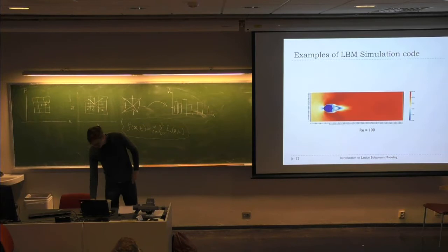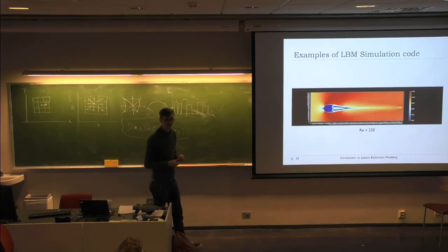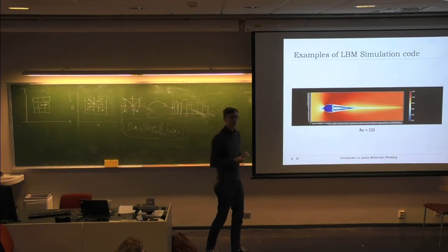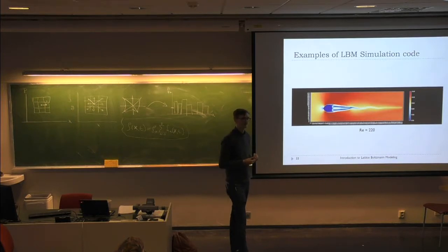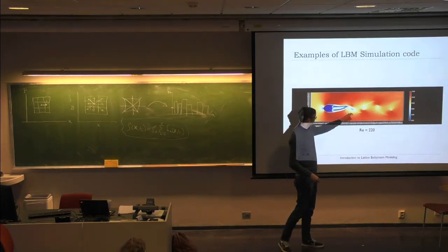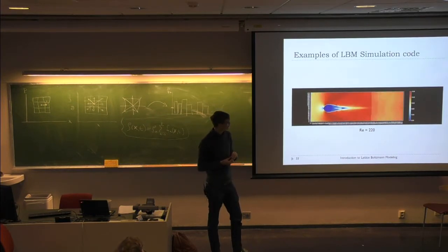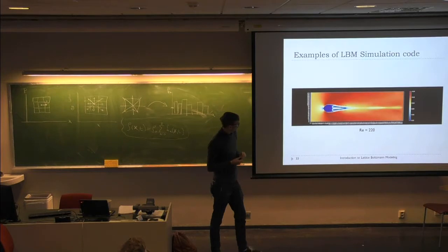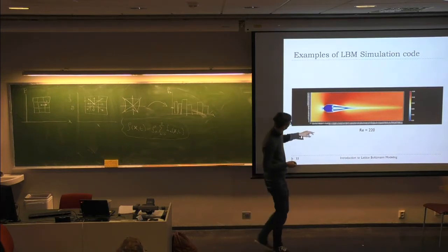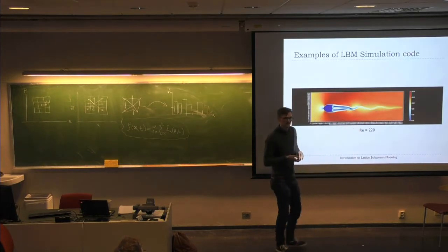So this is kind of a low Reynolds number. And here it's a bit higher velocity, right? Higher Reynolds number, yeah. It's lower viscosity. So you get the eddies earlier, and you also get more drastic eddies. And one thing I'd like to ask you: it looks like there's some numerical dispersion or some numerical instabilities here.